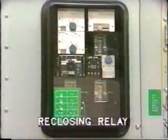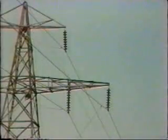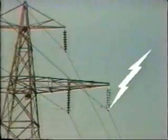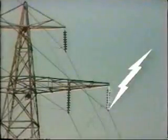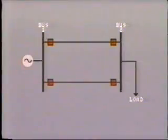One way around this problem is to bring the line back into service again as quickly as possible by automatic reclosing of the breakers. This action is based on the fact that most faults on overhead lines are temporary faults caused by a lightning strike or high winds or other climatic conditions. We have already discussed this in earlier tapes. When the breakers are reclosed after, say, half a second, in most cases the temporary fault will no longer exist.